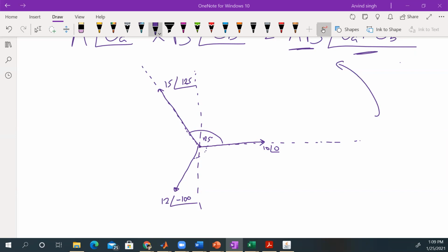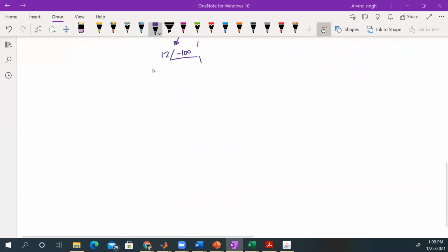So let's move on. Briefly describe what is a balanced three-phase system. So this is quite simple. A balanced three-phase system is where you have three voltages. The voltages and the currents on each phase are all equal in magnitude and separated by a phase of 120 degrees. The importance of this is that it sums to 0. So remember, when we're dealing with three-phase systems, one of the benefits is that if you have three generators, say,